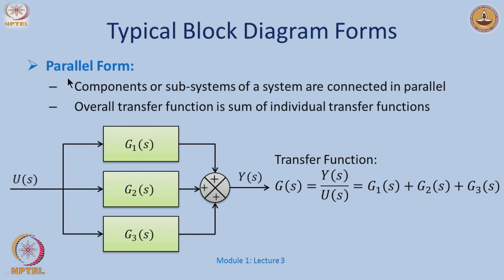Okay. So, this is what I call the series connection, or series interconnection, in which case the transfer functions just multiply. Similarly, I can also have components interconnected in parallel, and then, what would be the overall Y(s) over U(s)? Let us say that U via G1 generates an output Y1(s), here I have Y2(s) and here Y3(s), and by the definition of the summing block, Y(s) would be Y1(s) plus Y2(s) plus Y3(s).